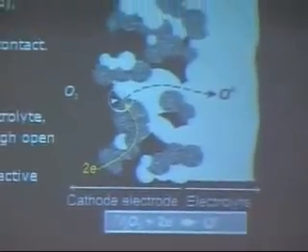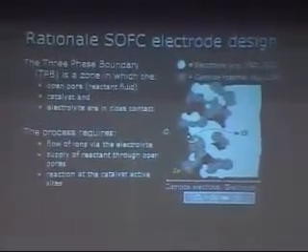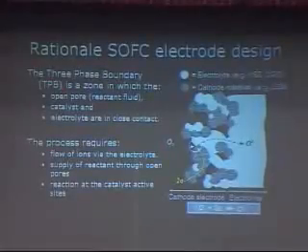And I would like to give you an example of the one on the bottom left, which is the design of the electrodes. This picture on the right shows, in white, the electrolyte, the solid part of a fuel cell, and the grey blobs are the porous electrode that is connected to it. And the critical thing to look at here is what is called the three-phase boundary. That is the junction between the electrode and the electrolyte.